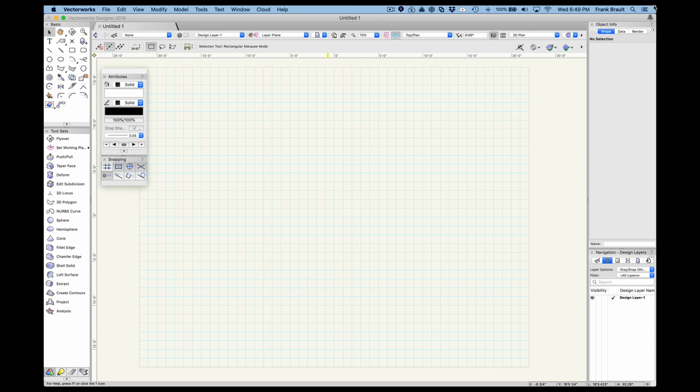So, for now, employ this simple guideline when starting to use layers and classes in your projects. Assign objects to layers to denote where the objects are, and use the object's class assignment to define what they are. It is also useful to think of layers as a container in which objects are placed, and to think of classes as a label or tag that members of each class wear. The program can be set up so that anything drawn in a particular class will take on the attributes assigned to the class.